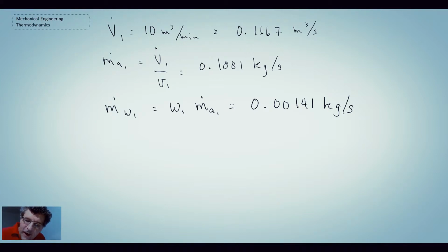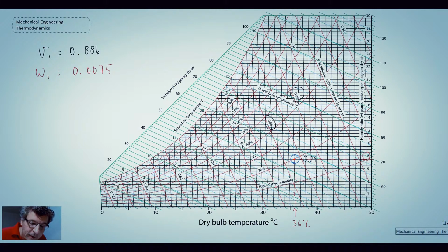What I want to do is go back to the psychrometric chart and pull off the value of the enthalpy. So let's take a look at enthalpy here. I'll use red because green might be hard to see. But enthalpy are the green lines moving up and kind of to the left. Our state is here, and we're going from there up to 90% humidity.